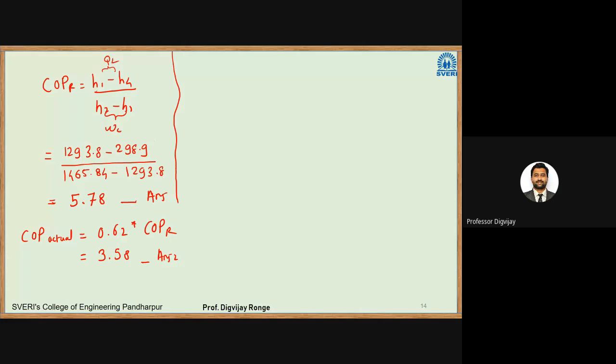Okay, next thing is we have to calculate the compressor capacity, how much compressor work is required. So see here, they have given the latent heat of ice. So we have to design one ice factory. Ice is being produced at 0 degrees Celsius. So latent heat of ice is given at 335 kilojoule per kg. Now, in this case, we have calculated the mass flow rate of ice.